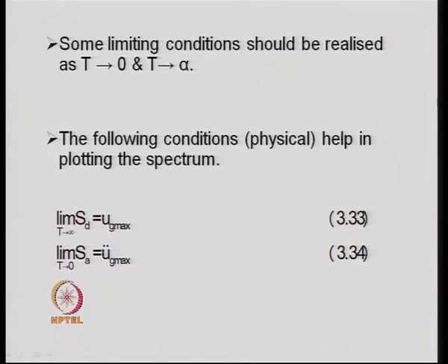The plot also can be obtained not against omega n, but against Tn, that is the period. In that case, the two inclined lines will get interchanged, that is the SA line would become the SD line and SD line will become SA line if we plot it against Tn.